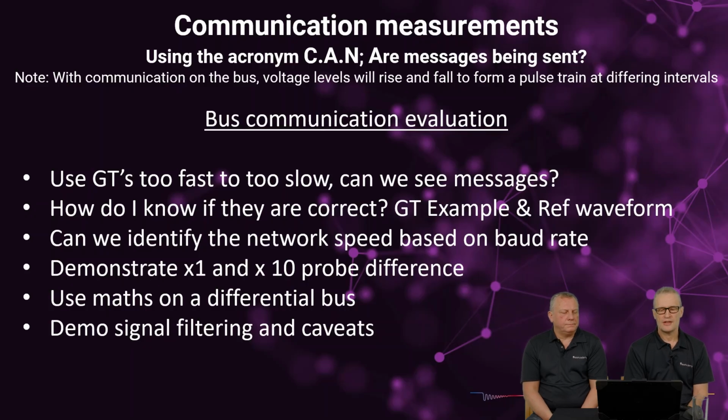And we'll demonstrate some filtering of waveforms and also some of the dangers around filtering. And we have a terminology, catch it dirty. So capture raw data, as dirty as it may be, as noisy as it may be, and then from that we've got raw data that we can modify. Let's not modify whilst we're capturing.